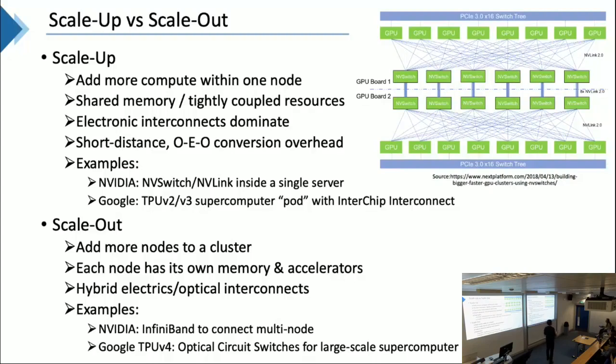The reason is, in one chip, all the signals are in the form of electronics. So when you want to convert your signal from electrics to optics, you need this optical-to-electrical conversion. It will introduce an overhead for this conversion, for example in power and area. So for short distance, we always use the electrical interconnect.